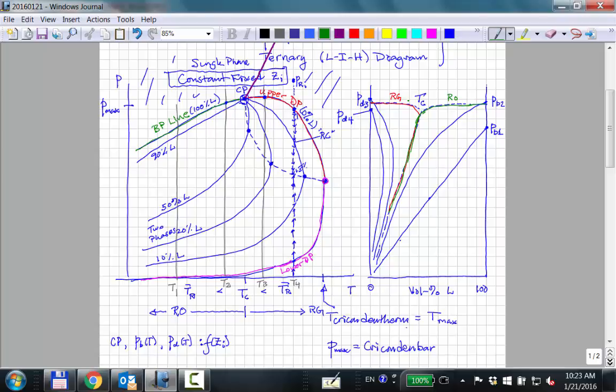So this is a phase diagram only in the sense that it marks the boundary. This would be PB1, PB2, so it's not really a phase diagram per se, but it does give kind of the nature of the two phases within the two-phase region. So it's the alternative to having these constant lines of percentage liquid. This is just a different way to represent the same information. And you may see it one way or the other.